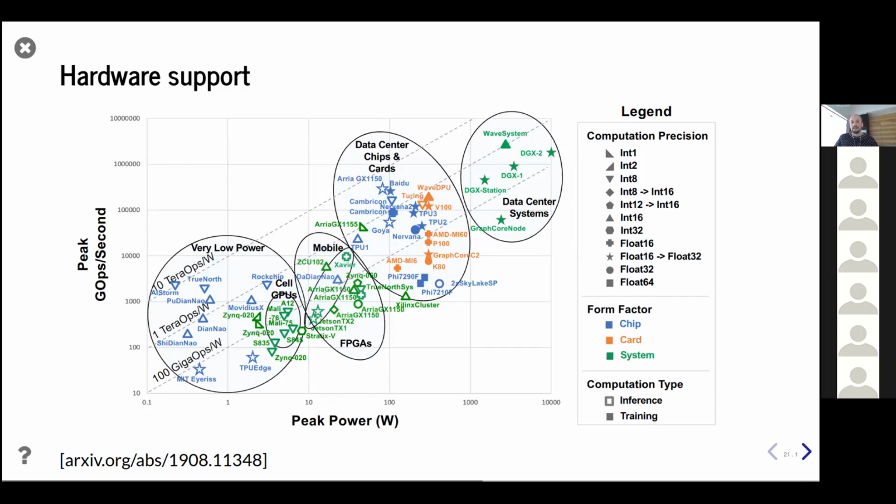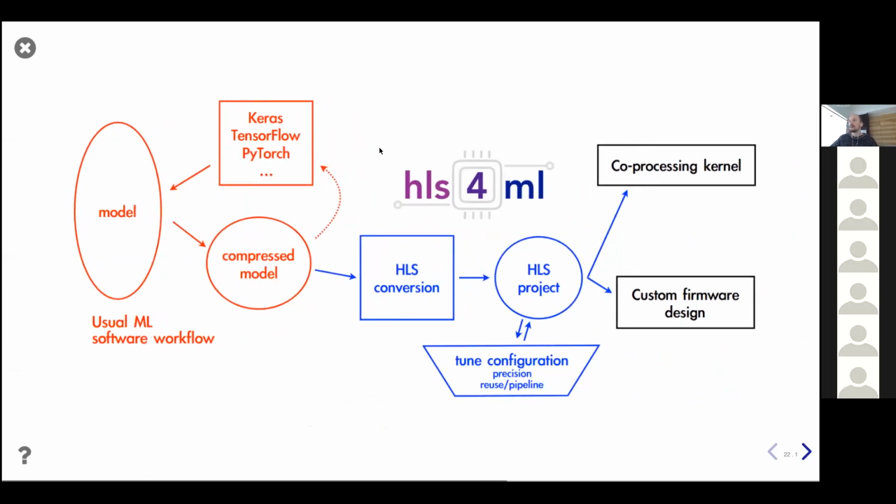So an example of this is this type of framework that is now available, where you can do these type of quantization procedures targeting, in this case, FPGA targets in a very automated fashion, where you go from the level of, for example, a Python-based trained neural network model, and you go all the way through this framework, and you arrive at an FPGA-based implementation for that particular model.